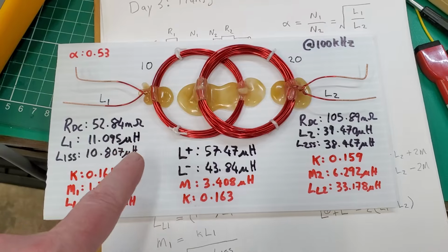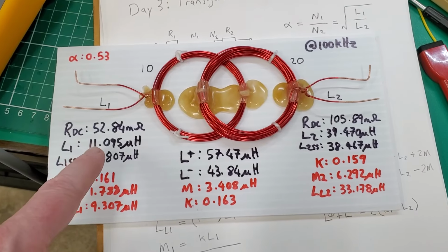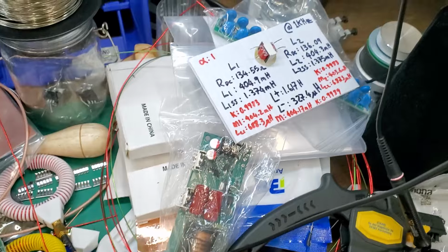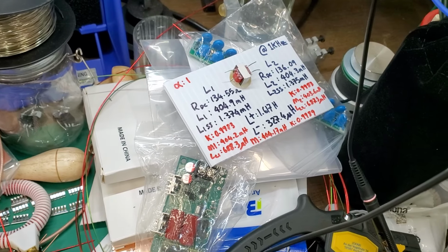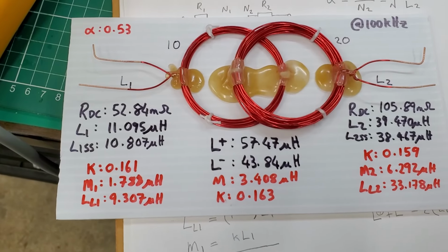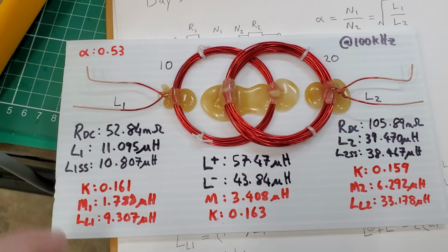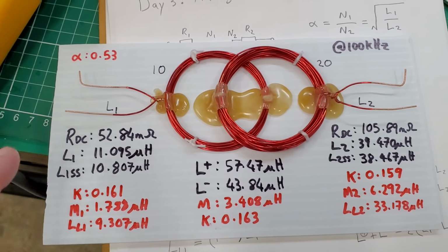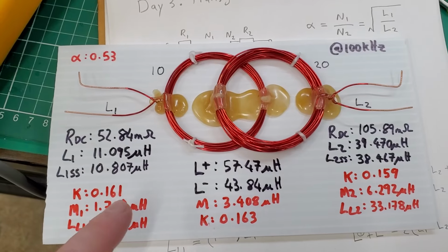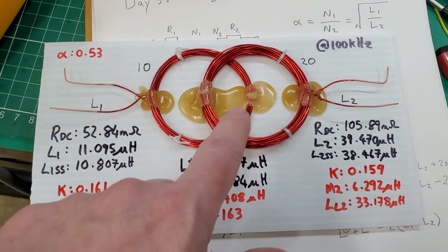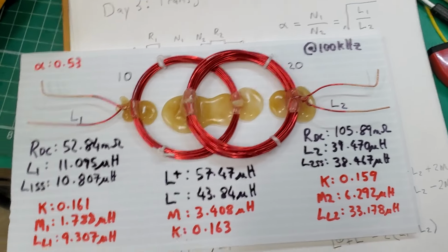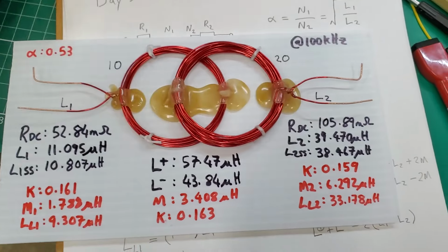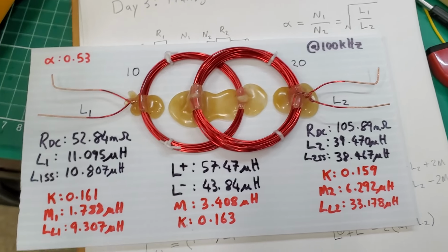And when you short it, you can see the inductance doesn't drop anywhere near as much as in this guy over here, where when we shorted the secondary, a great deal of the inductance went away. In here, only a fairly small amount of the inductance vanished. If you use that and do the math, you get a coupling coefficient of 0.16, because these are weakly coupled, right? Only whatever flux comes out of this guy and goes through this guy is joining these two coils together. The rest is just being returned back as self-inductance, and that is what the leakage term is.